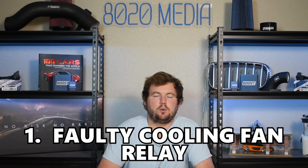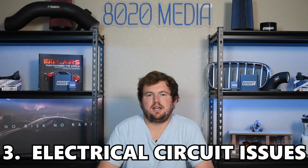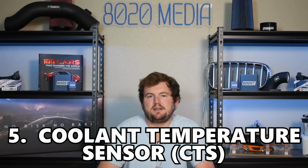The most common cause by far is going to be a faulty cooling fan relay. An electronic failure with the cooling fan itself could also trigger fault code P0480, along with any circuit issues. So this could be damaged wiring, loose connections, etc. And then another potential cause, one that's much less common than the others, is an issue with the PCM itself or a problem with the coolant temperature sensor.